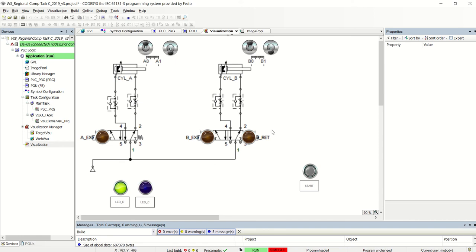So you can see it through the lights and through your imagination of the cylinder moving forward and back, that it's operating the correct sequence. The good thing is as well, you're in control of the speed of how you're clicking on and off these inputs, so you can really take your time to look through it. It's just important that if it is moving forward, this comes off first and then this goes on. If you keep that on and try to hit this, if you don't do it in the proper order, it can cause problems. So that's just one thing to look out for.